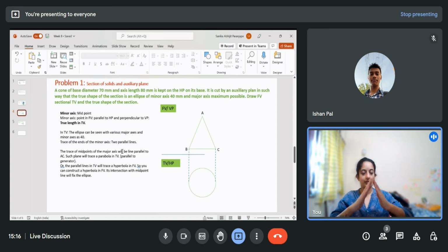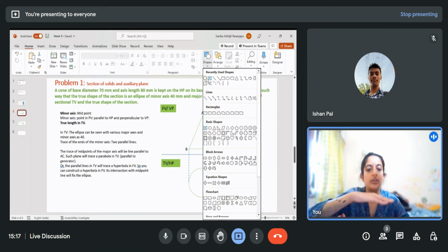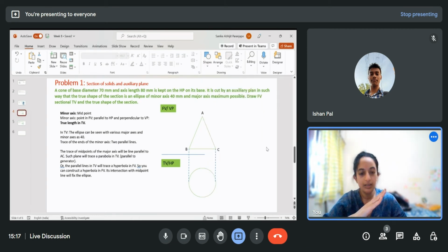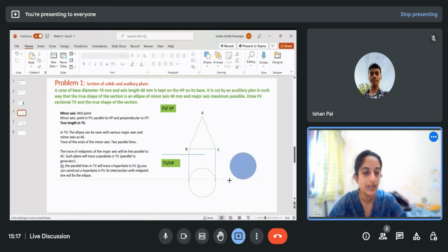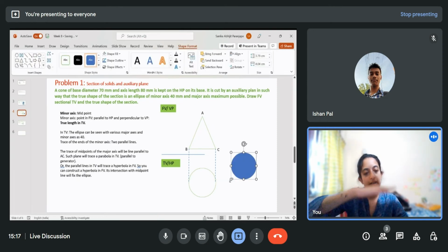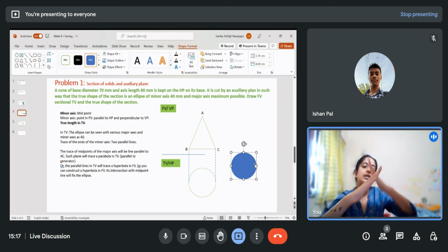So now what happens is if you have a cone like this and you have a plane like this. What I'm saying is this plane can make any angle little more than 0 and little less than the angle made by edge AB. So as you move up and up, if your plane is horizontal completely, you see a circle. As you rotate like this, it starts becoming an ellipse. So in top view, if the section plane is horizontal, the section will be exactly a circle.